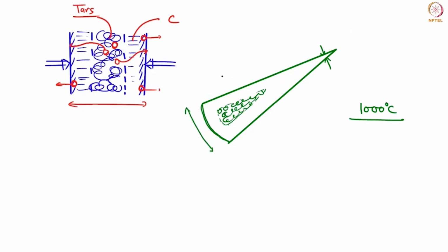So basically, due to this gradual decrease, there will be some point where you can slice it. After you remove it from the furnace, make a lot of very thin slices, and there will be a certain point where you will be able to see some porosity. So basically, whatever is the length at this point, that is the maximum dimension you can get.